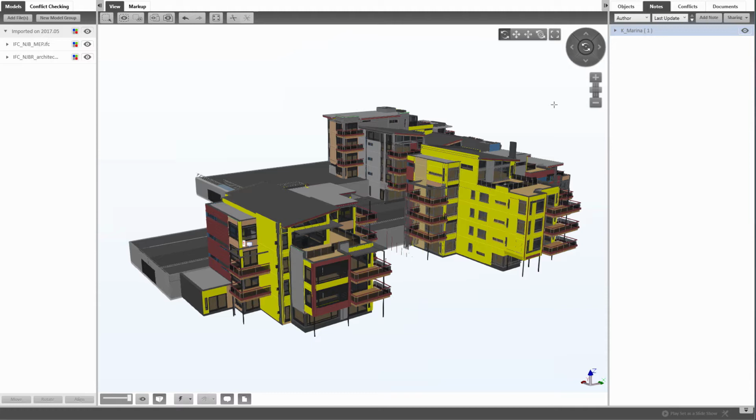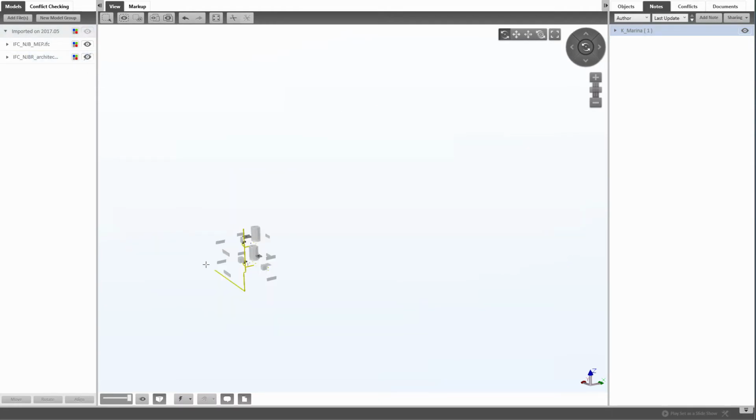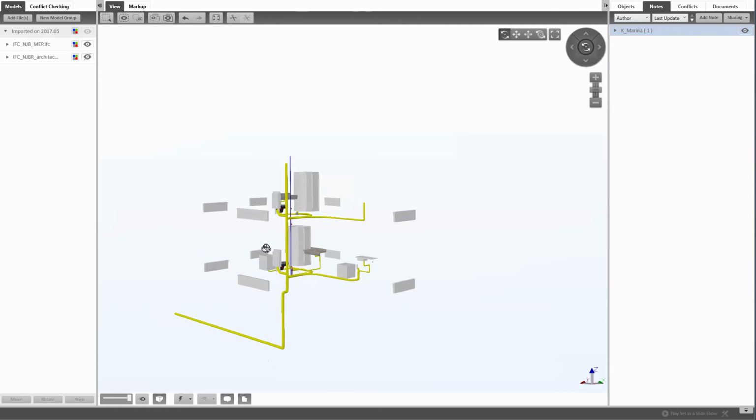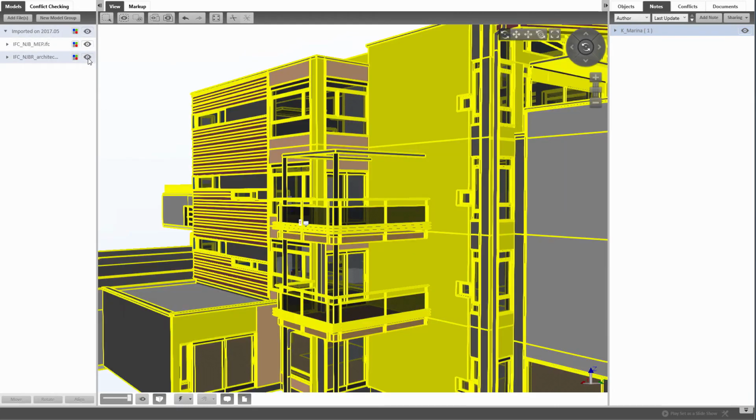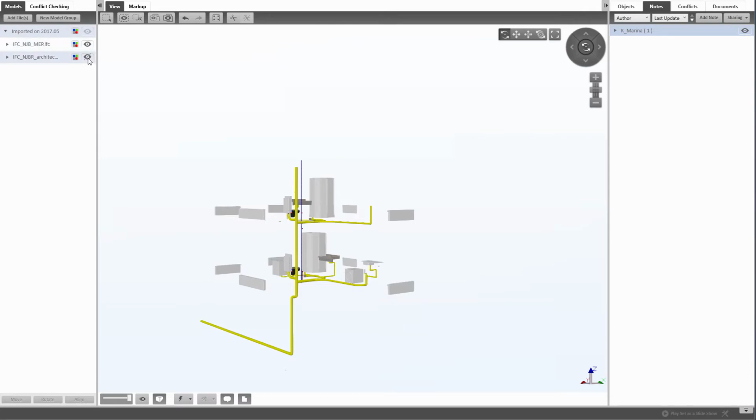Let's see how our markup issue can be displayed in software which supports BCF. Let's use the Tekla BIM Site IFC model viewer. First, we need to load the two IFC models that provide the collision detection in the project. The IFC models are needed to show the elements assigned to the BCF issue with their IFC Global Unique ID. Therefore, both the architectural and the MEP models are loaded in one BIM Site project.